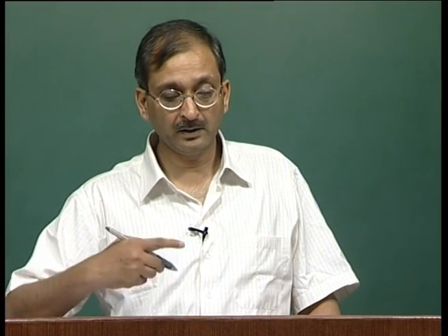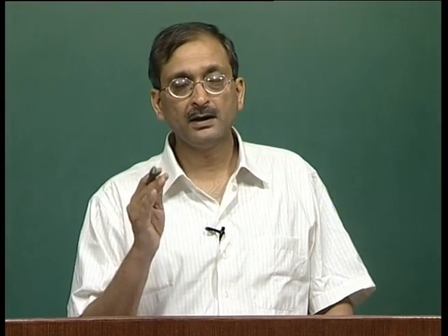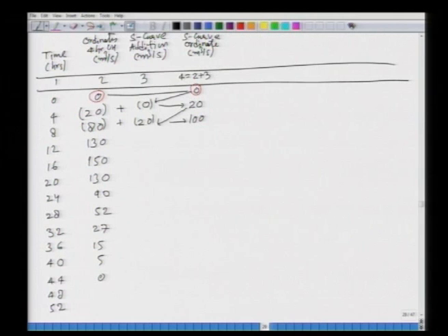This way, using only these 2 columns, one is the S curve addition column, the other is your directly S curve ordinate. This procedure which we are doing essentially amounts to the same thing as if you are lagging a 4-hour unit hydrograph infinitely, that is you are doing so many numbers and then keep on adding them. It has the same effect. So, let me quickly then do this.